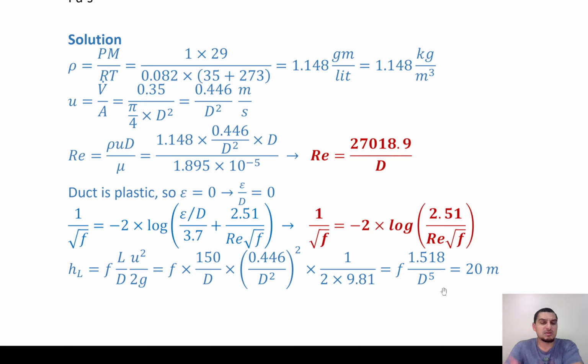and this is something we will discuss later about the choice of the diameter. But the point I want to make here is that we mentioned before the pressure drop is very sensitive to the diameter in case of laminar flow, and it's much more sensitive in case of turbulent flow. So again, increasing the power by 1 is not a small thing. It's a big deal. It's a very big deal.